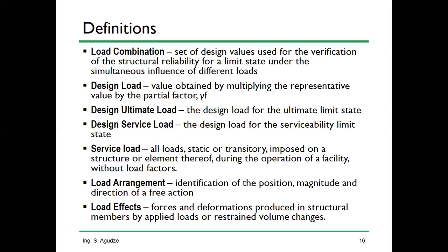For example, at the hostel, anytime they are playing games or doing a certain activity, you see that all the students will leave their rooms and they will now be on the corridor. So it means that the room there is empty, only dead load is active, but the corridor is now having a full dead load and full imposed load, right? So when it comes to the load effects, the effects of the loading, bending moment, shear force, axial force and so forth, that's the load effect.